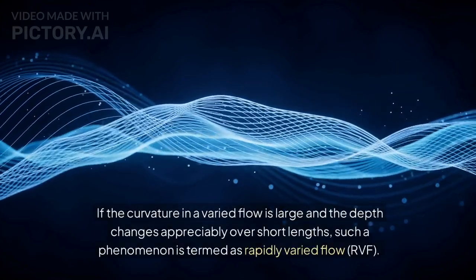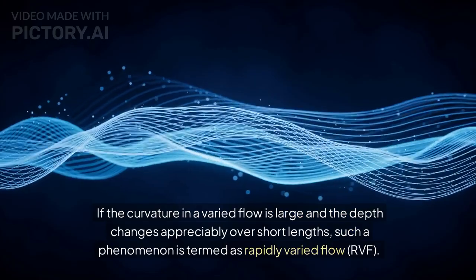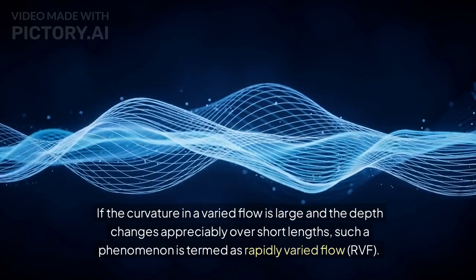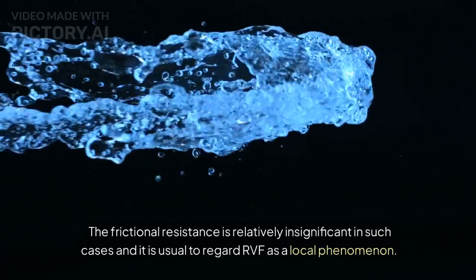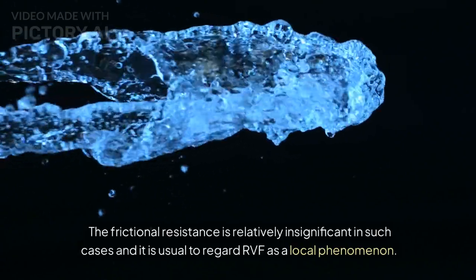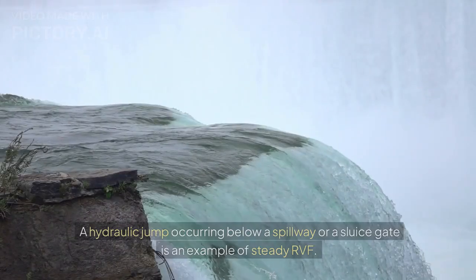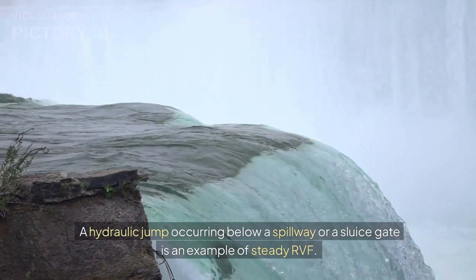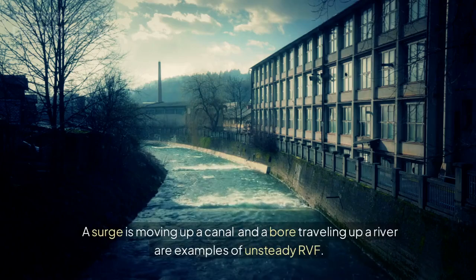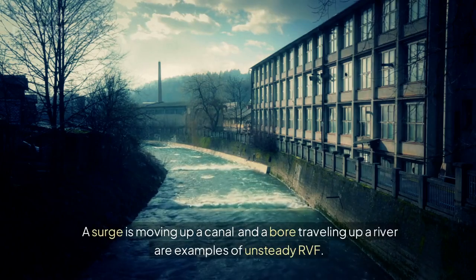If the curvature in a varied flow is large and the depth changes appreciably over short lengths, such a phenomenon is termed rapidly varied flow, RVF. The frictional resistance is relatively insignificant in such cases, and it is usual to regard RVF as a local phenomenon. A hydraulic jump occurring below a spillway or a sluice gate is an example of steady RVF. A surge moving up a canal, and a bore traveling up a river, are examples of unsteady RVF.